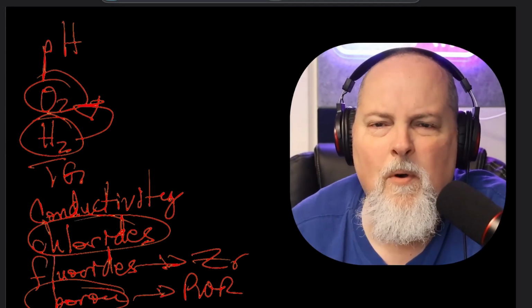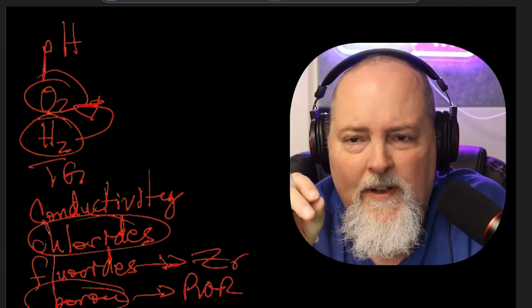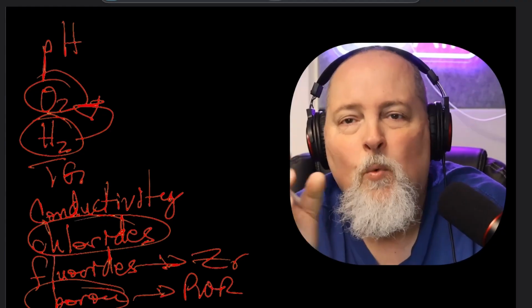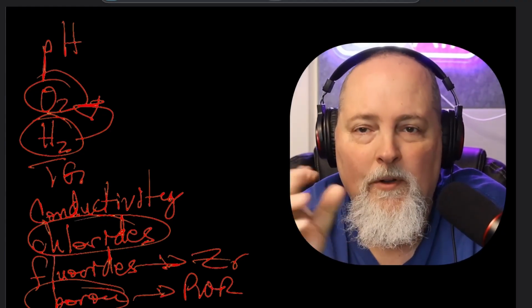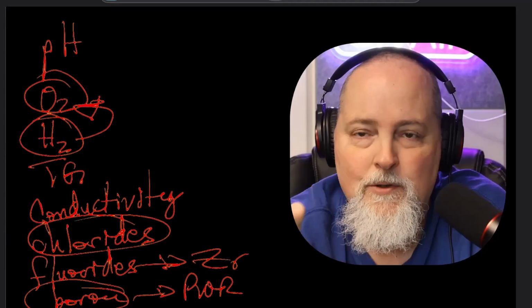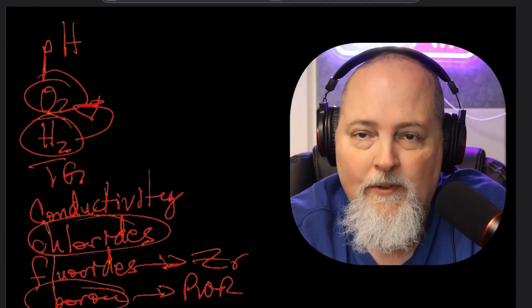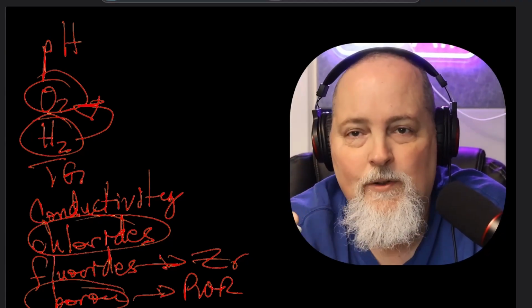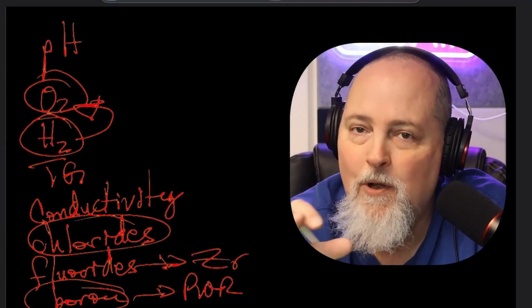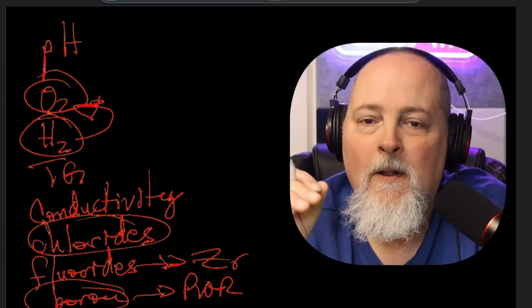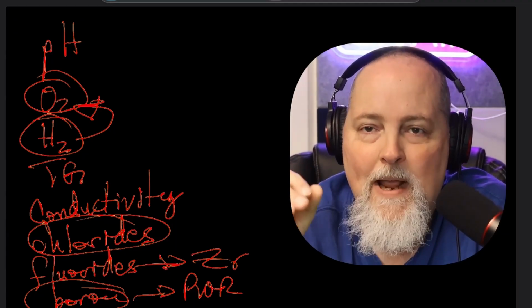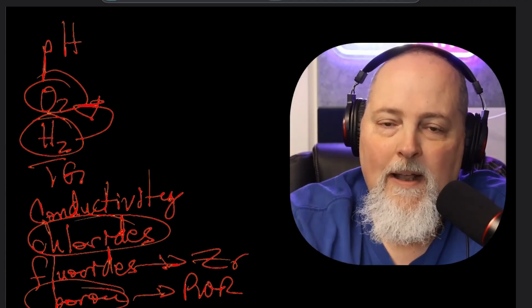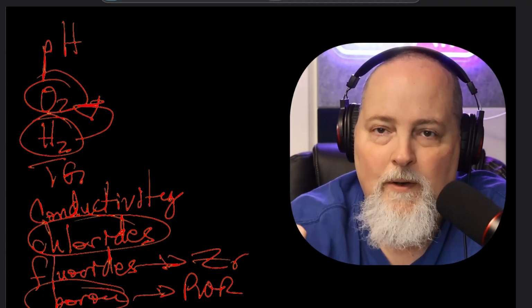So in a BWR, your material says that there's no boron in normal operation. I want to point out, we do have boron, what we call SLC tanks, the standby liquid control tanks, that are full of boron solution, borated water, and we can inject those in a BWR. We just don't unless there's an emergency. So when we try to scram the reactor on a BWR, we have our logic buttons, and we push those logic buttons and the rods go in.